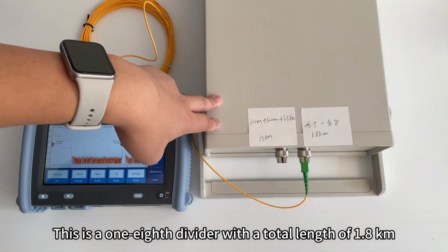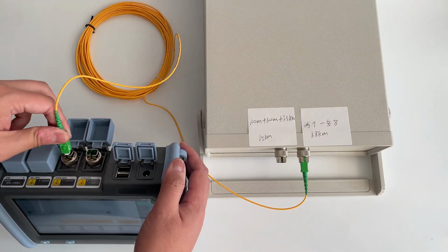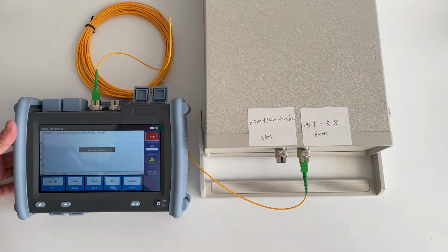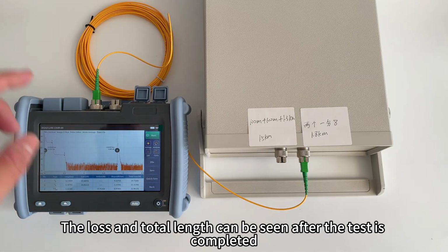This is a 1-to-8 splitter with a total length of 1.8 kilometers. Access wavelengths. Select the wavelengths. Click to test. The loss and total length can be seen after the test is completed.